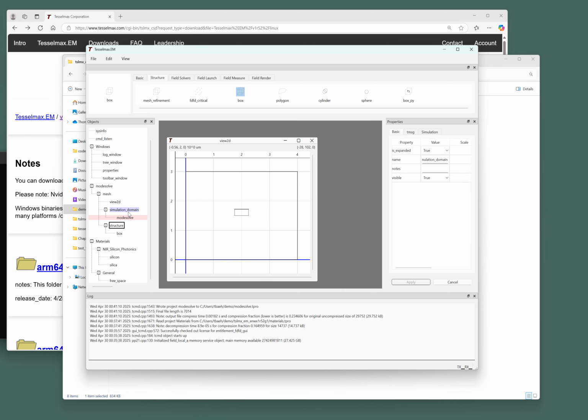I should add that the actual absolute value of E and H oftentimes do not matter. For example, if you're looking at bend loss, you really just care about the modal coefficient extinction as you go around the bend. Really, any problem in linear optics, even if there's loss, it's really not too important what the actual absolute units are. But I think it's good to know, just so that you have an intuitive sense for what's going on with the physics. So we've made an effort to make that very transparent. But at the same time, it's probably not usually something that you'd use. Okay, so we're all ready to do a mode solve. I'll just save the file here. What we now need to do is to specify our computation device.